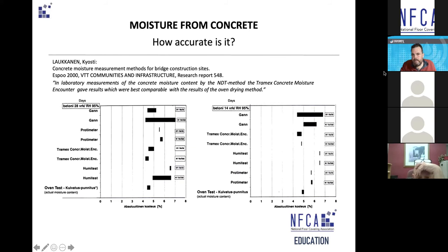But basically, they're called signal loss meters. They're made for repeatability of readings, like our moisture encounter, our ME5, and they're made for finding the moisture rather than a measurement like the concrete meters. But anyway, if you treat it like a calcium chloride test, in other words, you make sure the surface is abraded the way it should be. Sometimes they use a carborundum stone just to abrade an area for testing. That chart tells me that the Tramex is actually very accurate for what it is.